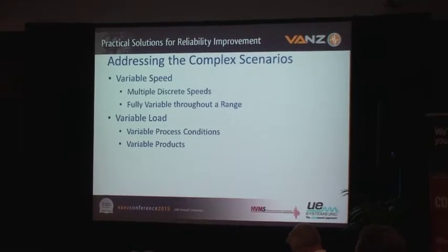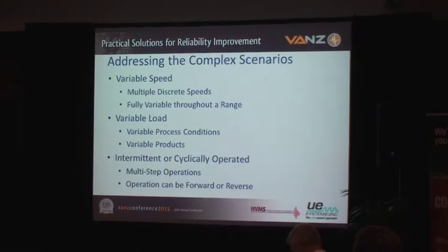But eventually we would get to the point where we've got enough data at each of the normal speed load conditions to be able to statistically compartmentalize them and then combine them so that we can do the appropriate thresholding, and again, focus on change. Because we want to make sure that when we see change in the data, we're seeing change in the data because something in the machine has changed, because that's really what we're looking for, as opposed to all I'm seeing is the fact that we've changed how we're running the machine today because we're running at a different speed or a different load condition.